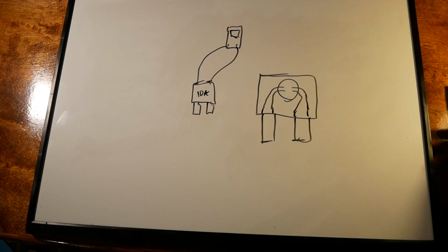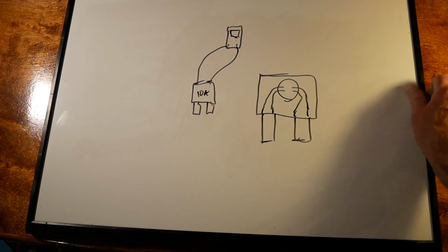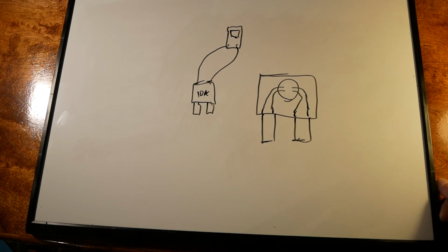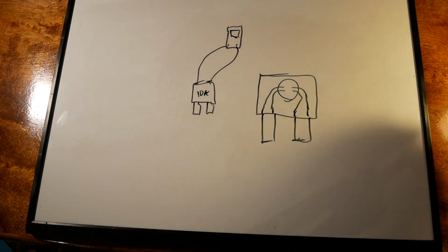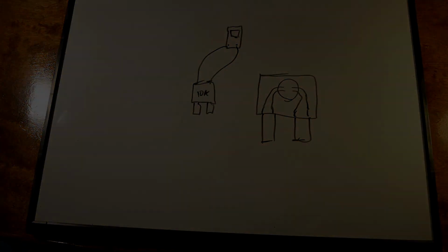So, in this case, if you're looking for a parasitic draw in a vehicle, you can just start checking fuses in the fuse box. If there's no current flowing through a fuse, there should be no voltage drop across it. You'll read 0 volts. If there's current going through a fuse, then you'll start to read voltage, and the higher voltage will indicate higher current flow through the fuse. And you can accurately determine parasitic draws as low as 100 milliamps using this method.